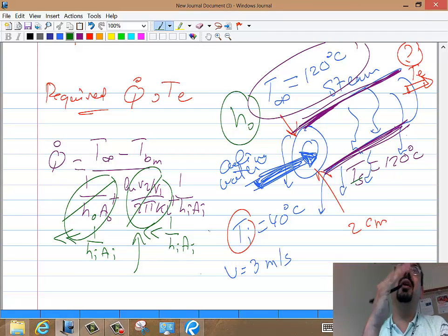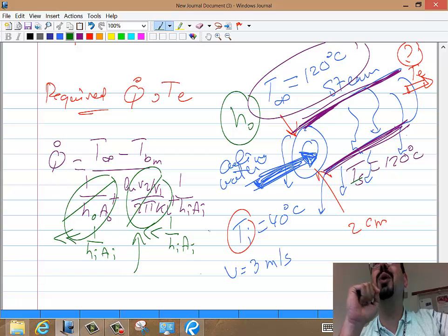So Brandon is saying, well, you would feel very silly if convection resistance is like 100, and then the conduction next to it is 0.001. And you'd say, okay, now it's 100 plus 100.001. And you spend like 50 minutes, not 15 minutes, trying to calculate the ln R2 over R1 over 2 pi KL, because you had to interpolate to get the K because you didn't know the temperature. And so that's a good question.